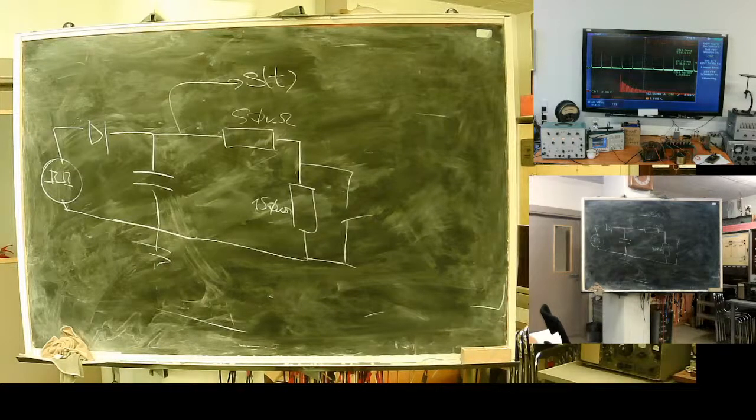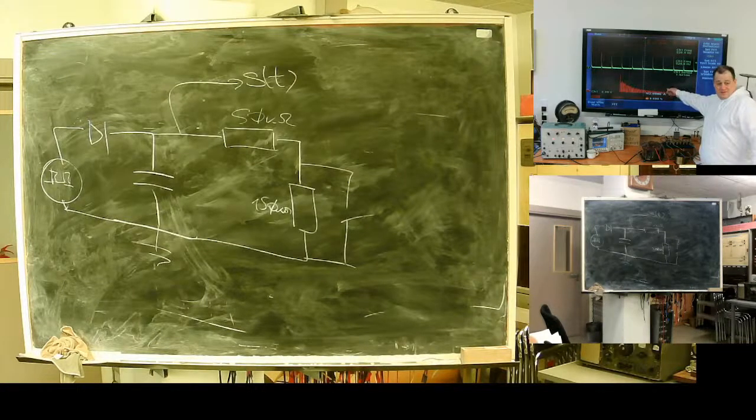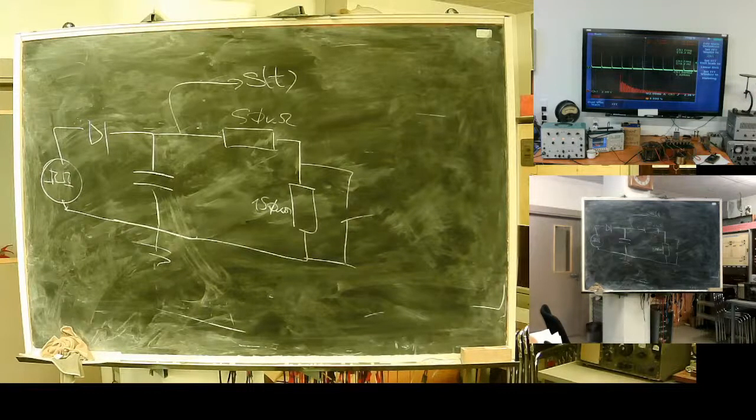Or resonance. The history of power system design knew a lot of cases where a resonant circuit was at some 100, 200 kilohertz. At a low frequency, everything works fine. When at commutation high-frequency components appear, they cause resonance and fast degradation of semiconductors.